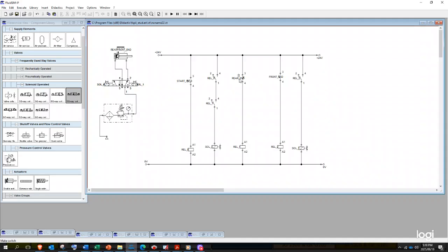This limit switch we use to advance, hence it's connected directly to this solenoid 0, because everything on this side falls under the advancing process. So there's nothing deep to it, guys. This is a method for presenting your AND operation when you have two actuators needed for the same process. So this is how you connect them. I hope I am clear enough.